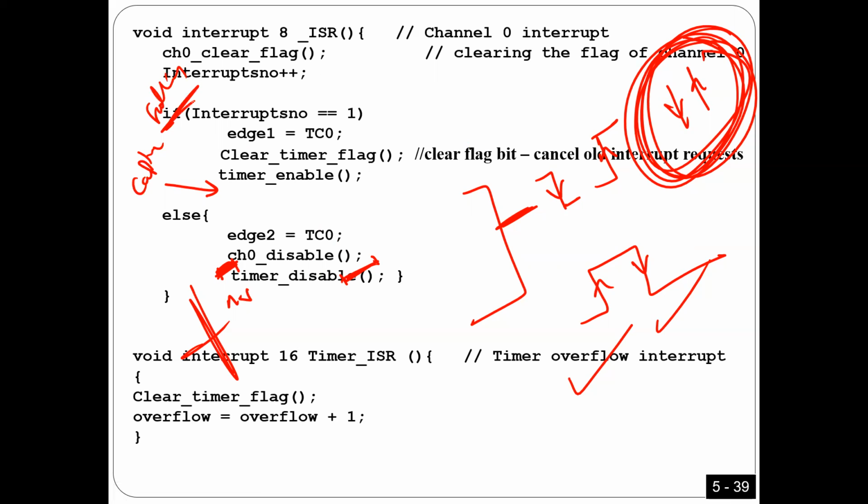Any question? Do you get what I'm saying? What I'm saying, guys, is, let me say it again: how can you configure the pin? You can configure the pin to capture both rising and falling. This may be okay if your signal looks like something like that, because I'm going to have rising and falling, one here and one here, and that's okay. However, it may not be okay in other cases.